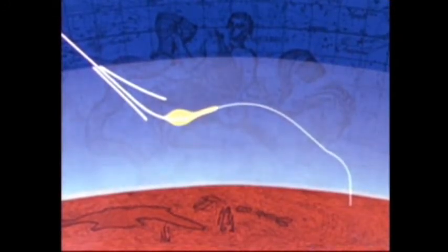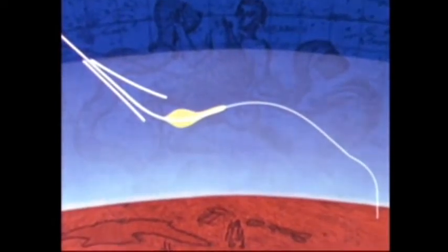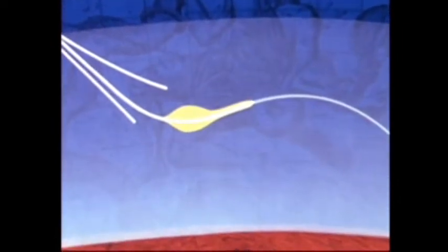As the spacecraft approaches the skip, the aerodynamic forces become less and approach zero, so aerodynamic control approaches zero. It is during this first control period that the real determination of where the spacecraft will land is made. To understand this, let's take a look at a flat map of the Earth. This point represents the target, that is, the point at which the spacecraft should land. This is the landing footprint, or area in which the spacecraft might land, at the beginning of the first control period.